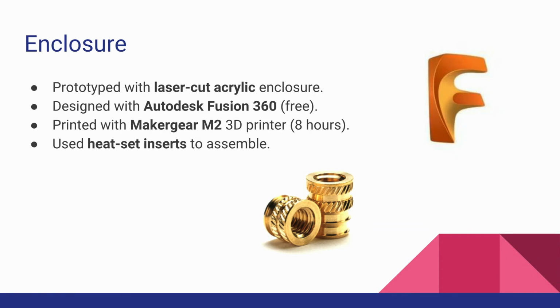I want to shout out to these heat set inserts, which I didn't know about until I started working on this. And when we open this, I can show you what they look like. The little brass pieces like this are basically the nut part of a thing. They're available in M1s and M2s and M3s or whatever. They've got these little knurls on the side. So you 3D print a hole for the nut that's just the right size so that they sort of half fit in there.